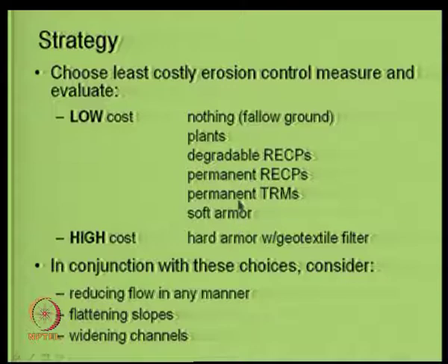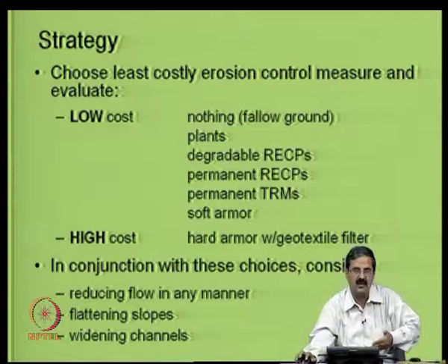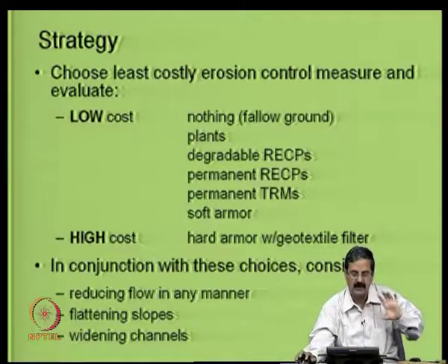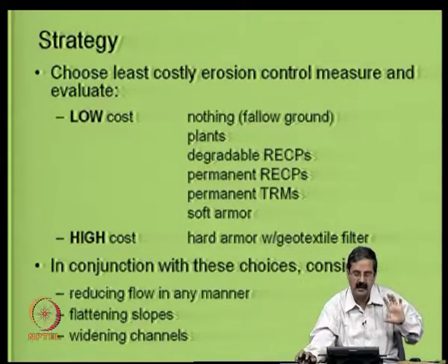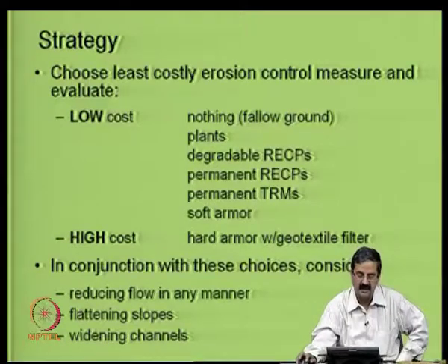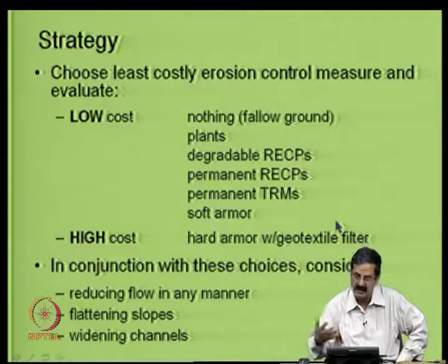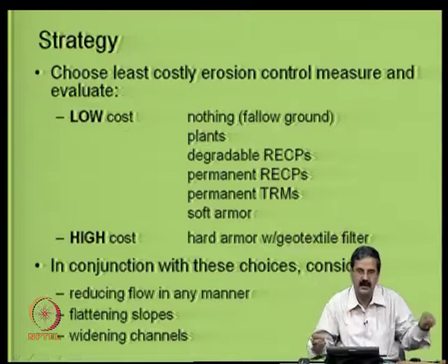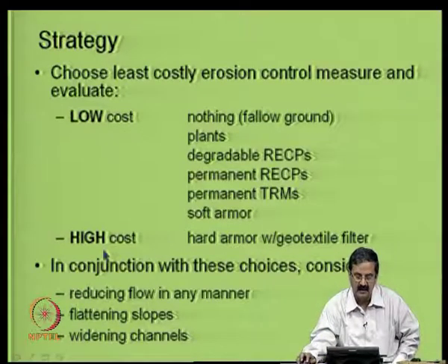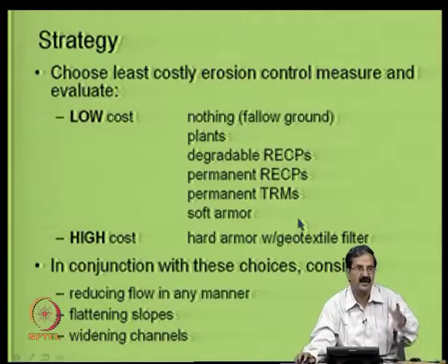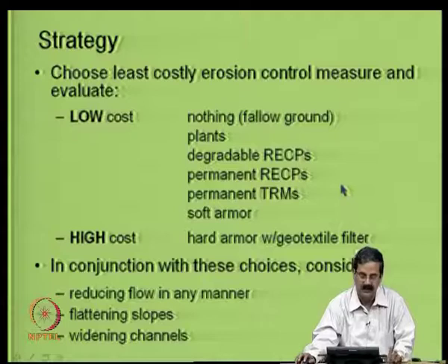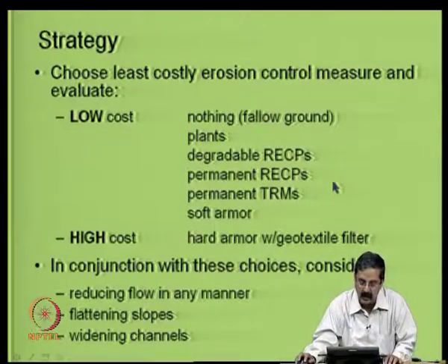We also can have permanent systems where you can design what the velocity of flow is likely to be, and how it should be permanently anchored. There should not be any difficulties. You have again two options. One is soft armor, in the sense you try to contain, and then a suitable anchoring system is there. Hard armor you can also have with or without geotextile. It can be like hard facing, hard pitching. Stone pitching is something like armor, hard armor we call it.